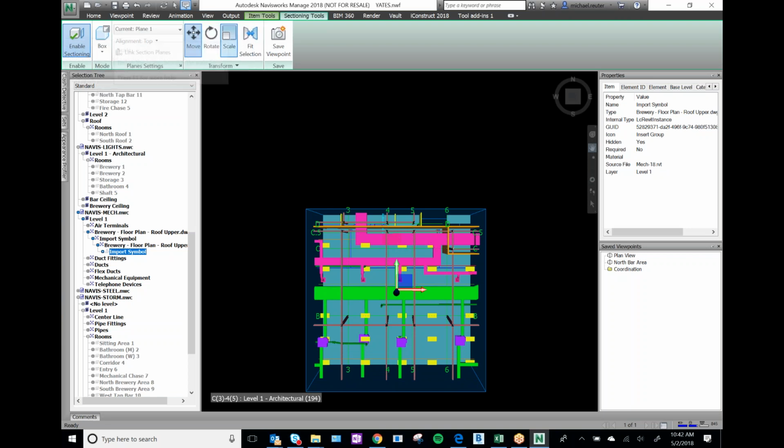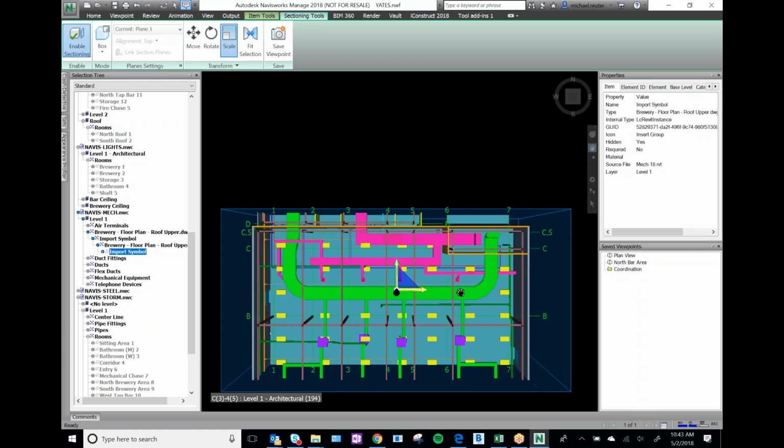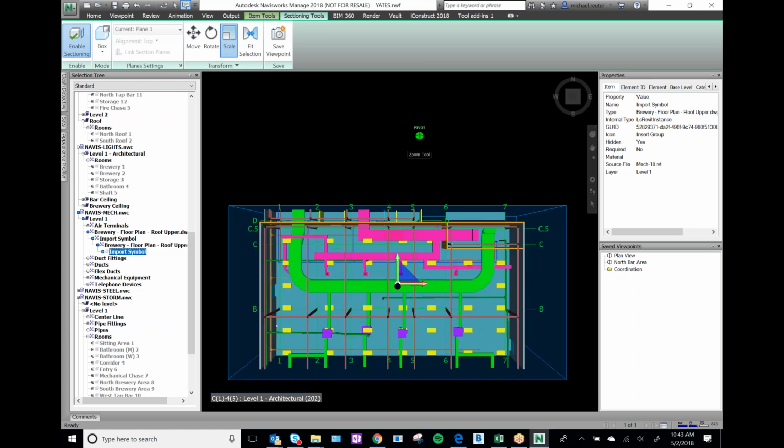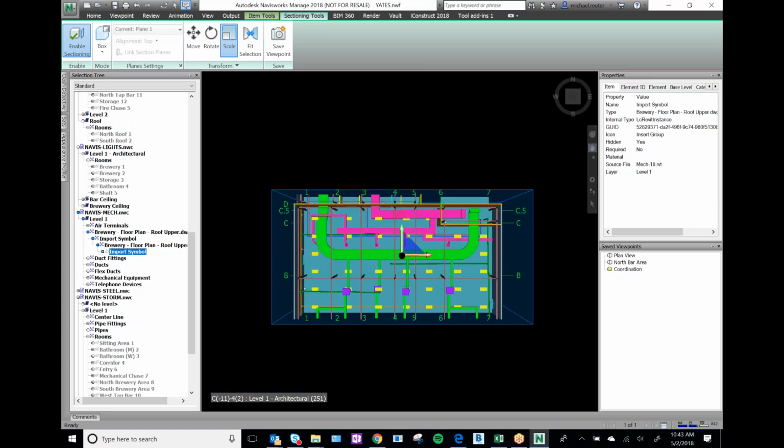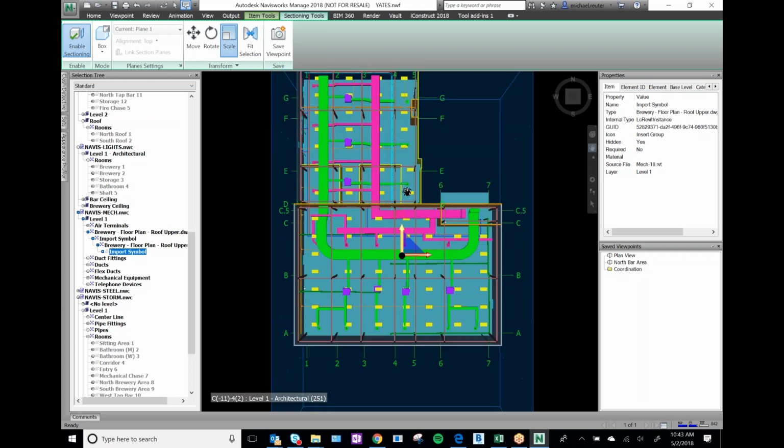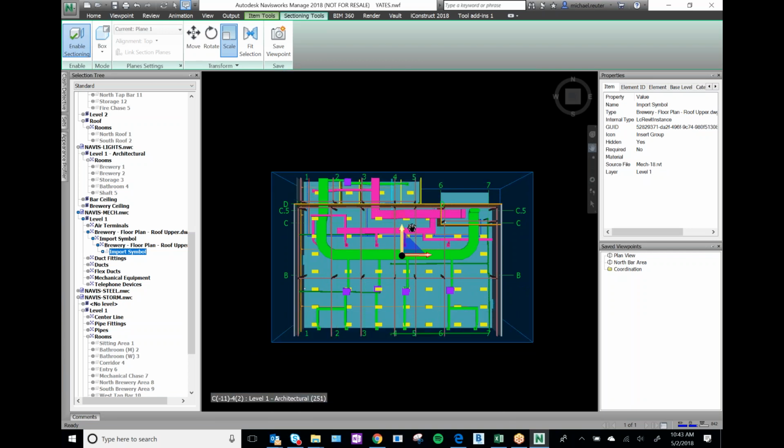I've got it where I want it, but I want this box to be bigger. We can hit the scale button right here. So we had move picked, and if you couldn't move anything, you need to select one of these. The way that you know it's selected is if it's blue. So we've moved it to where we want it to go. Now I want to scale it. Same thing. Once I roll over it, it turns yellow. I click and I drag, and it's going to enlarge or shrink the section, based on which way I go.